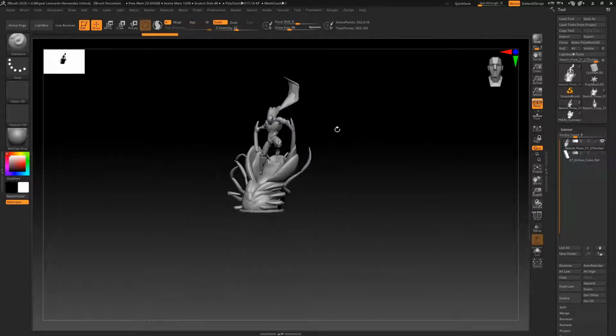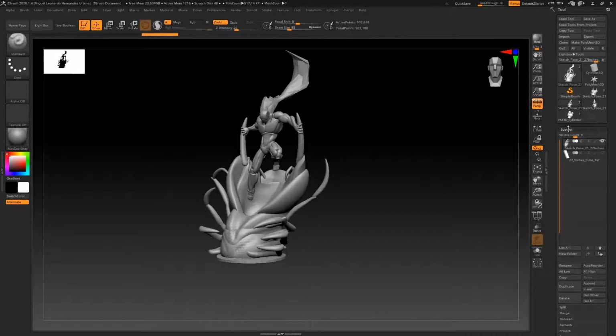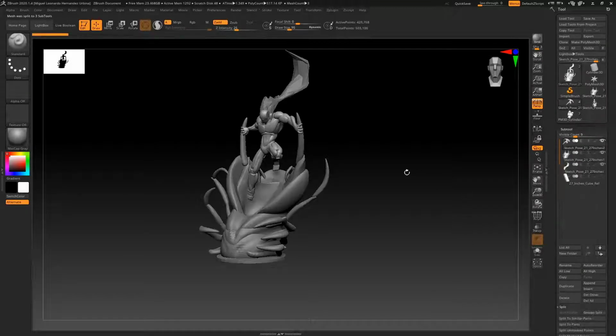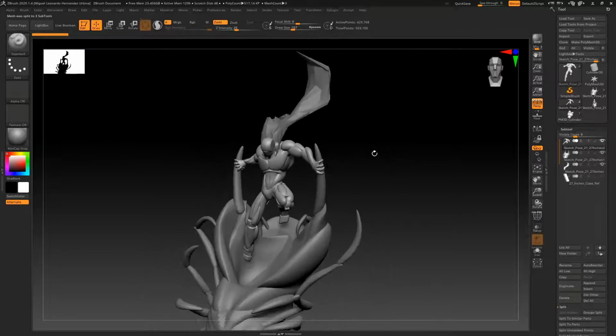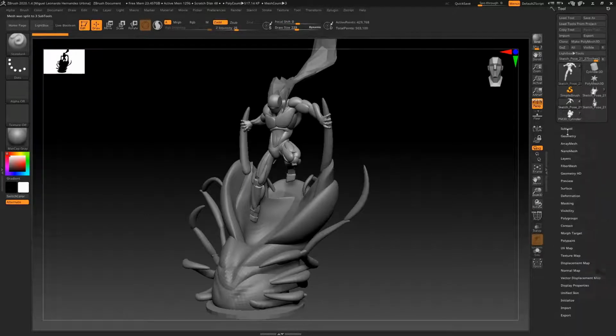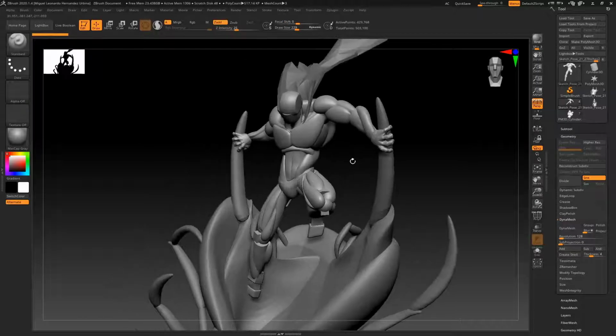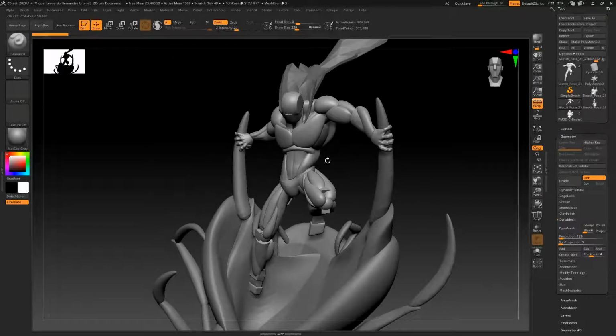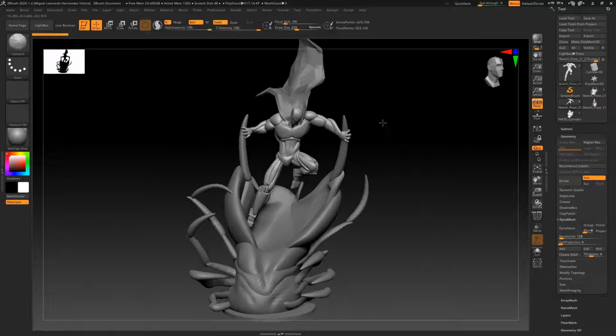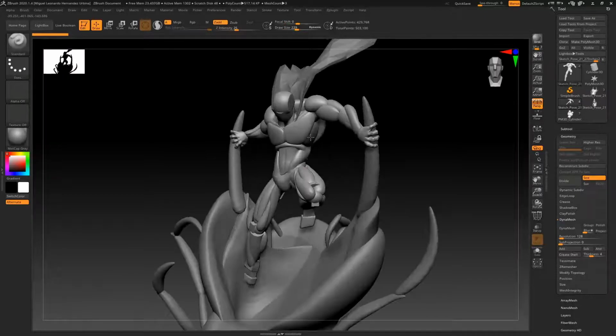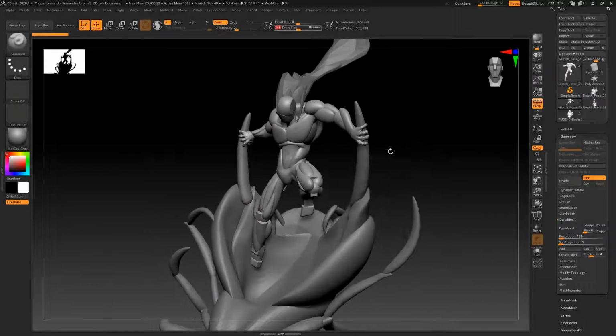The other thing is the use of the Dynamesh tool, or the split tool. If you want to Dynamesh something, be careful when you have a huge file, because if you apply Dynamesh on these huge files and move to the highest resolution, your computer will crash. Imagine the computer trying to analyze this huge geometry and recompute all that geometry into a huge model.